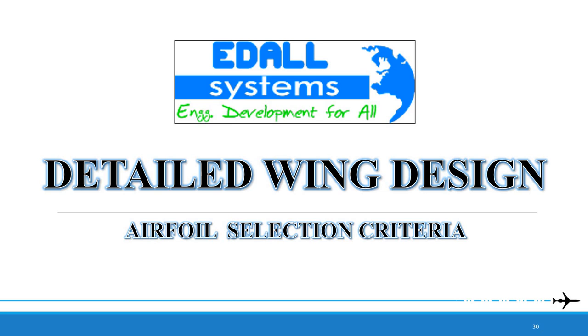In this session, I will discuss airfoil selection criteria. The airfoil selection is an important part of overall wing design. Selection of an airfoil for a wing depends on flight requirements, whether the wing must be designed for subsonic, supersonic, or transonic flight design requirements. The designer must also consider other requirements such as airworthiness, structural, manufacturability, and cost requirements.